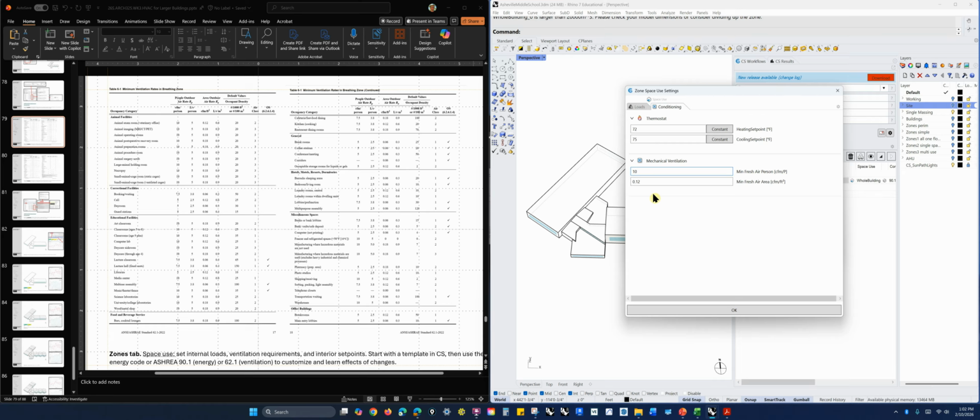If we bring in some of that air, it's going to be a considerable heat loss as we dump the 72 degree air out. That's why we use some kind of energy recovery ventilation, and that can be set in the mechanical system. But right now we're just saying, okay, this is how much air we're moving, and that's going to have an effect on our peak loads. Okay, so these are the variables that we're setting for the space itself, the space use, and the volume of the space.